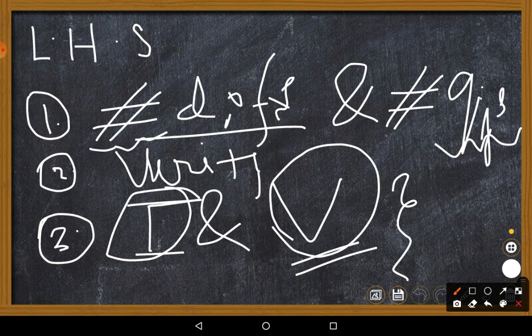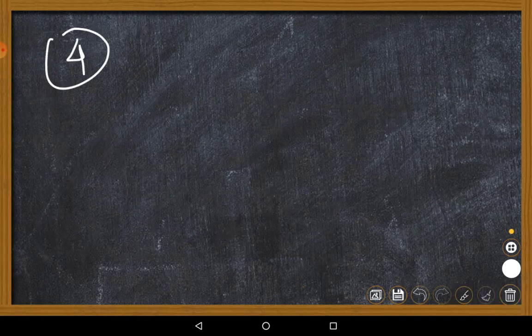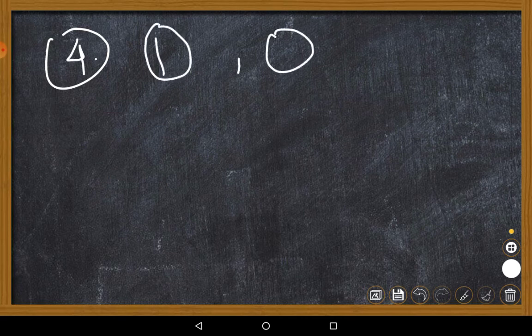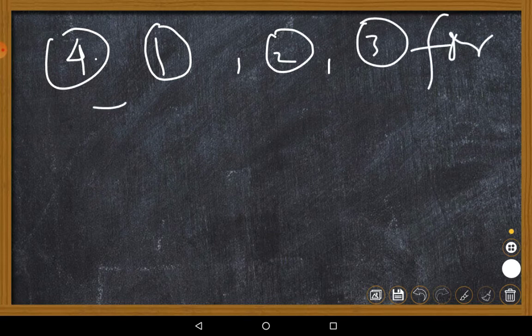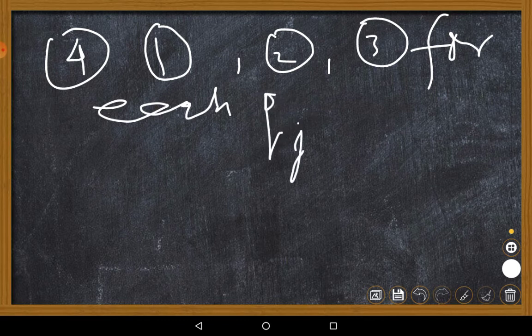After this step, the fourth step is for LHS computation. You simply find term 1, term 2, term 3 for each q_j. Remember this, for each generalized coordinate you do this for q_j. By that I mean, if you have two generalized coordinates, the whole Lagrangian process will be done twice as per holonomicity. So for each q_j you compute each of terms 1, 2, 3.